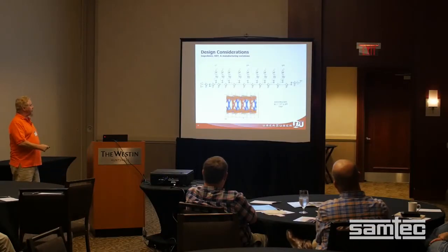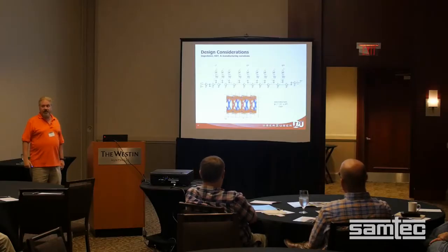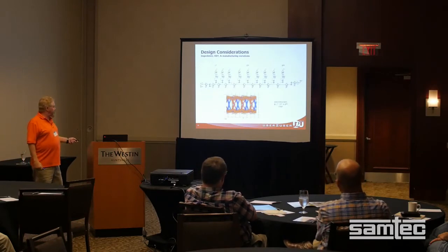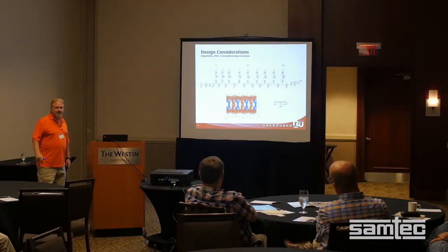Now, all of these go away if you take the capacitors off the models. It's an easy way to test it. And with the IBIS models, that's easy to do. I always have a collection of IBIS models that say NC, no caps. And then no inductance. I have models that are just perfect. They're just there. They're an oscilloscope. And then I build upon this and see what happens. Because if you take the capacitance off, these all look really nice. Questions on what I'm saying here? Because you got to simulate all this stuff.